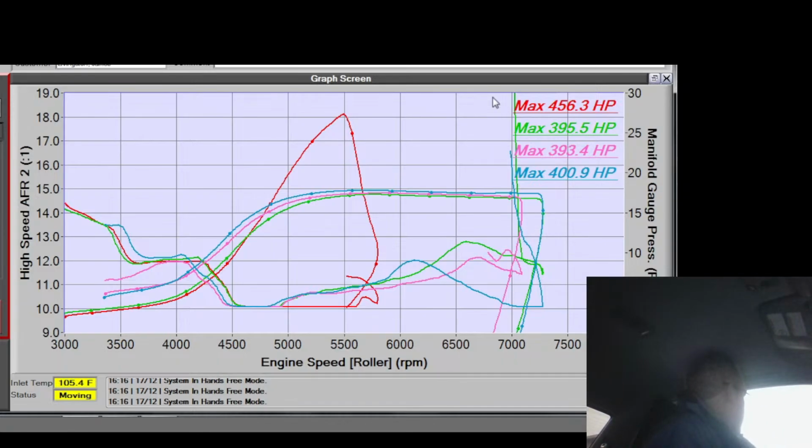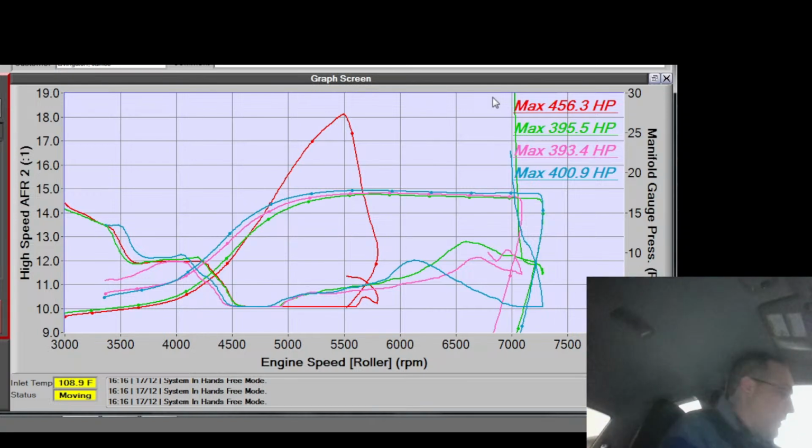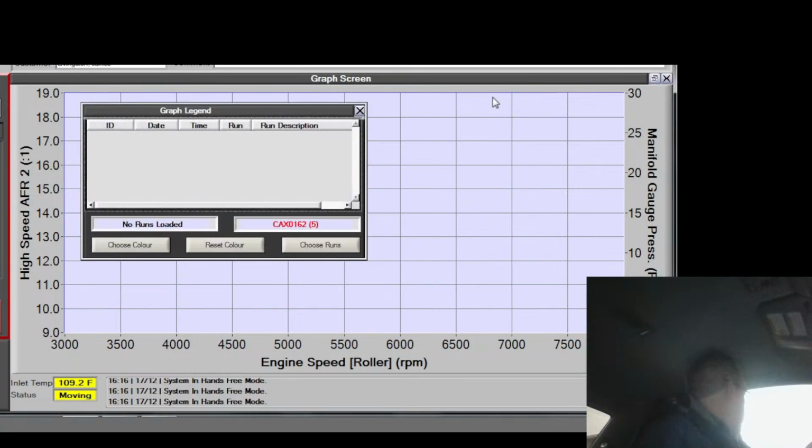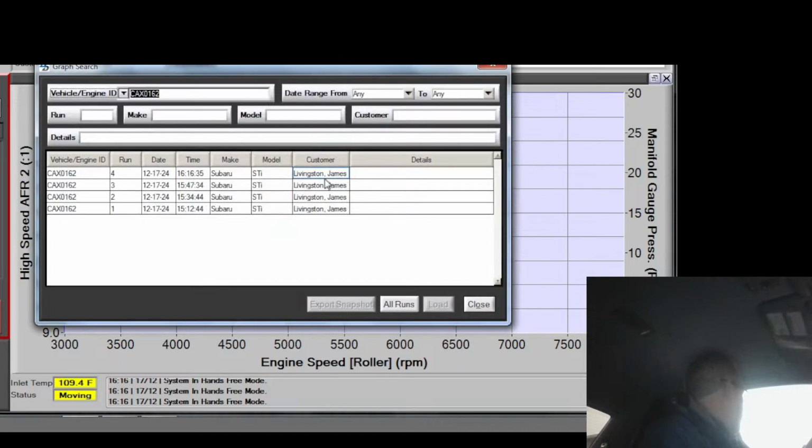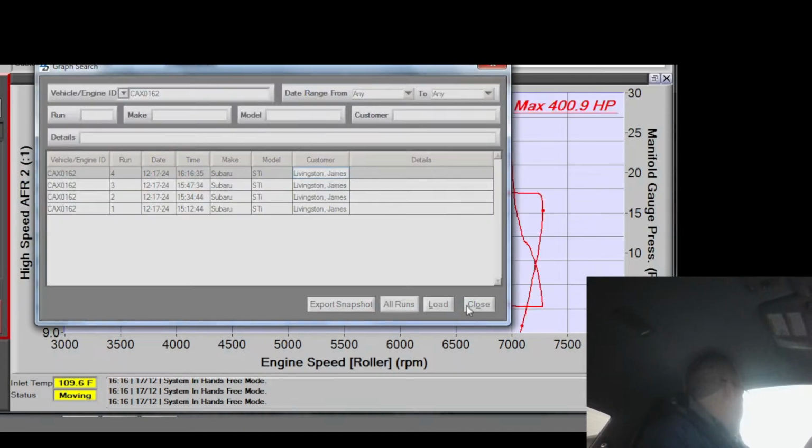Yeah, something is not right. This VE curve is very typical. In fact, we're actually reaching the atypical VE curve here, and the results of the air fuel curve are not matching at all.